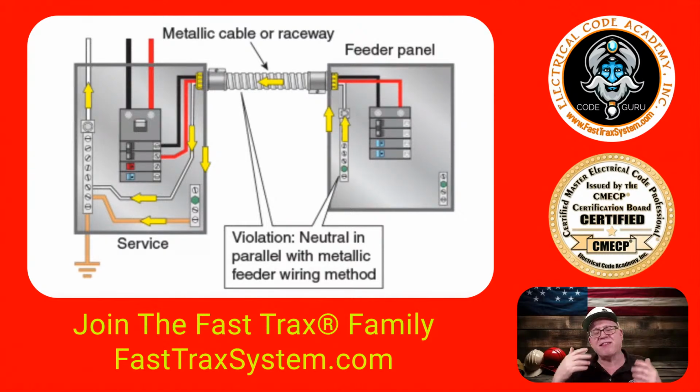Okay, so all of this is listed in 250.118. I encourage you to pause the video, go look at it, and see the different allowances. Now, if this was rigid metal, intermediate metal, if this was EMT, all of those types of raceways and tubings are listed over in 250.118. But this is not an MC. This is not an AC cable, because typically AC cables wouldn't be in larger than 1 gauge, so we would limit the size, okay? But it may be an AC cable if this was a smaller size remote distribution panel.